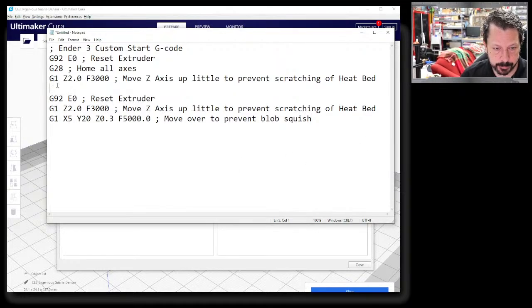So let's say that what I want to do is G1 to make a movement. Currently the nozzle is at the home point. We just homed everything and it's 2 millimeters above because it's at Z of 2. So G1, let's move everything off from that corner. So we can use the 0.1. Well, actually, let's start at 10. So we're at 0. Let's go to 10.